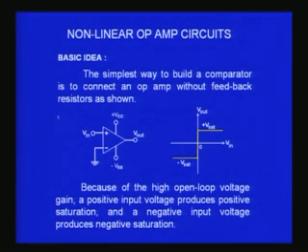If I now make the V in negative by inverting the terminals at the power supply input source and then keep increasing from 0 in the negative direction, you would find that because it becomes less than the inverting input, the output will go to minus VCC, because now in magnitude the input is larger, and therefore the output goes to minus VCC.